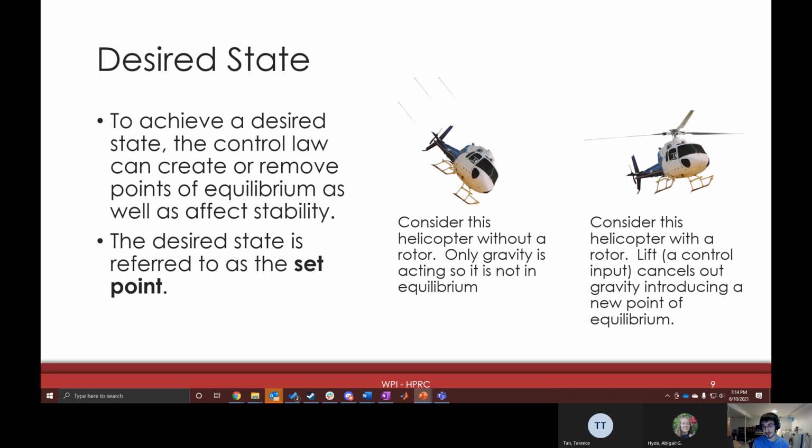And there's more complicated things like that. In general, those are called time of flight sensors, which basically determine how far away you are based on some signal you're sending and getting back. There's also things like LiDAR and infrared sensors, which all work in that same kind of manner. Radar. You could also use something like a barometer, which senses change in pressure to detect whether or not you're moving up and down vertically. And that's a pretty common aircraft instrument, because you can sense whether or not you're gaining or losing altitude.